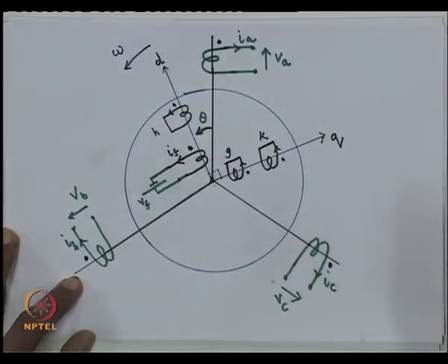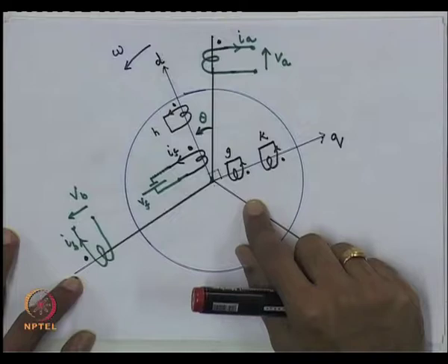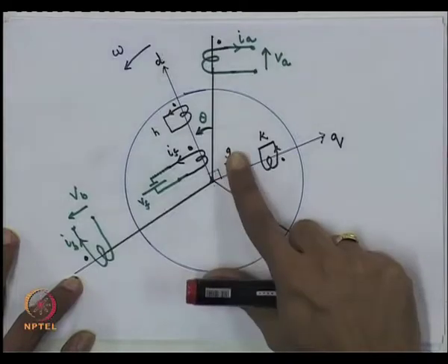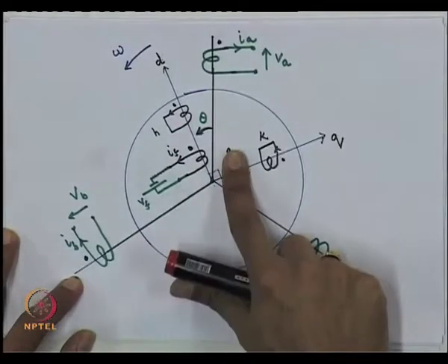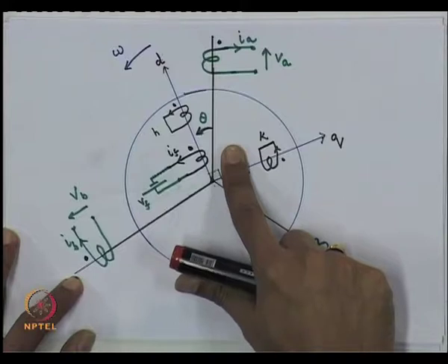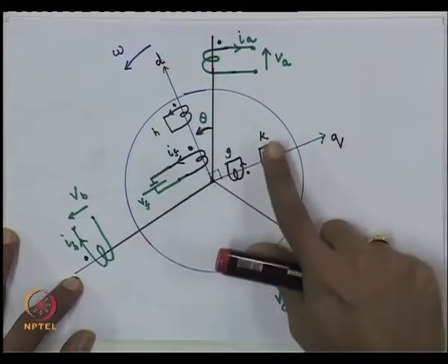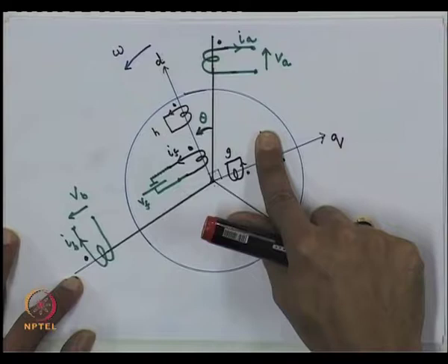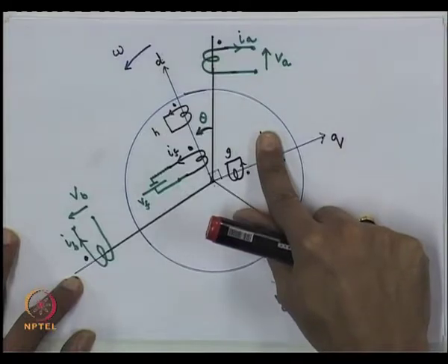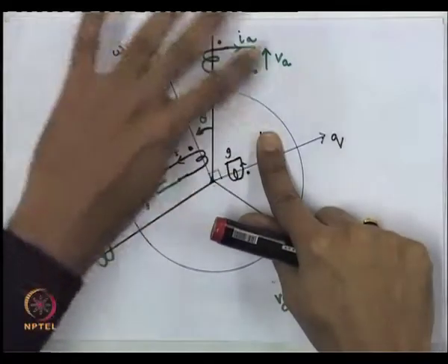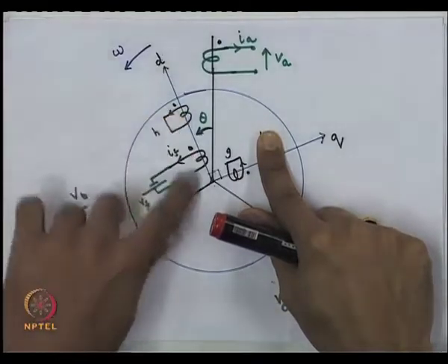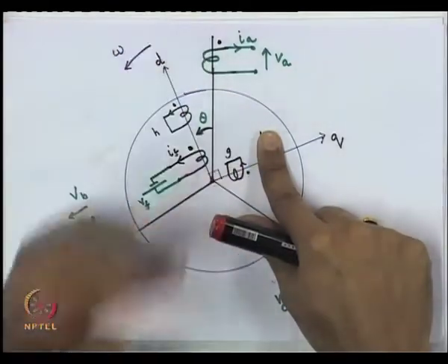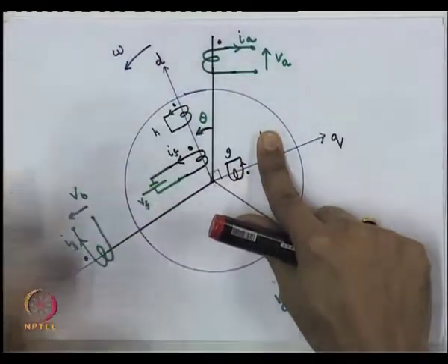In fact, for hydraulic turbine machines, it may even be possible to represent the whole system by a lower order model, that is, using fewer circuits. In some cases you may neglect the K winding when modeling a hydraulic turbine, because a model consisting of these windings with their parameters can accurately represent the kind of observations seen in the tests.